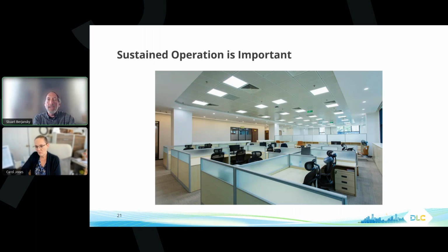So there are a lot of benefits to utilizing standards. Standards like DALI, and also DMX, which I forgot to mention earlier. DALI and DMX are kind of the two digital standards that exist here in the US. DMX comes out of the theatrical world, but is showing up more in the architectural world now, primarily when used for color, like RGB color mixing. DMX is also really fast, so you may find it a lot on outdoor installations where you have color changing on bridges, buildings, things like that.